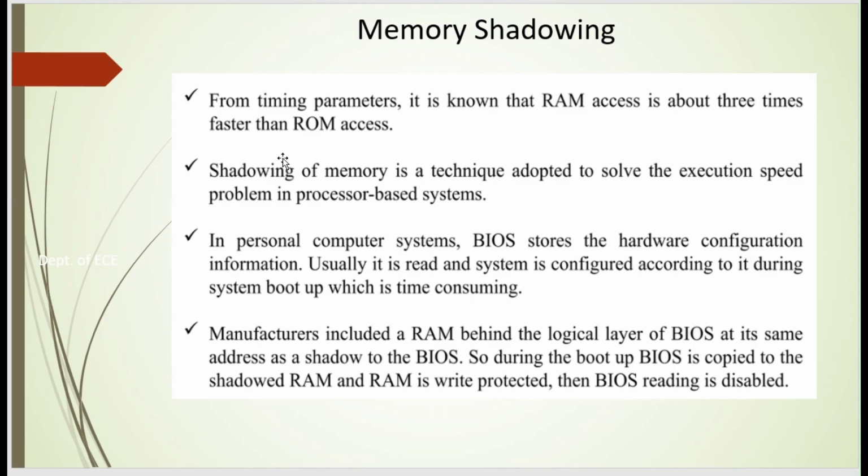In personal computer systems, the BIOS stores the hardware configuration information. Manufacturers include a RAM behind the logical layer of the BIOS, with the same address, as a shadow to the BIOS. So during the boot up, BIOS is copied to the shadowed RAM and RAM is write protected.